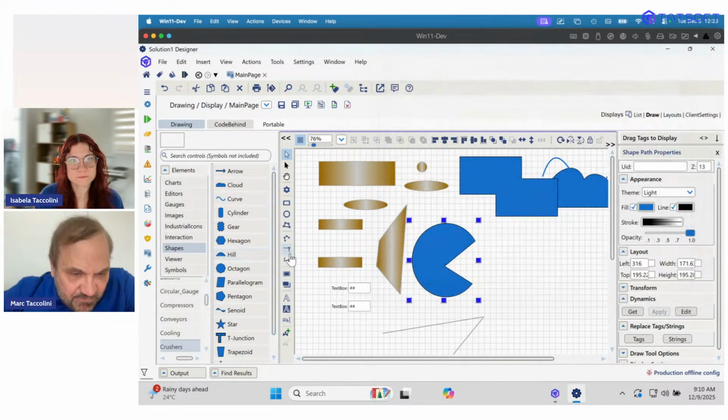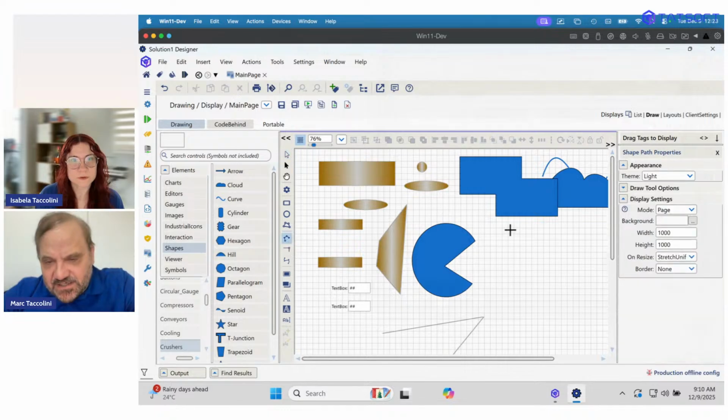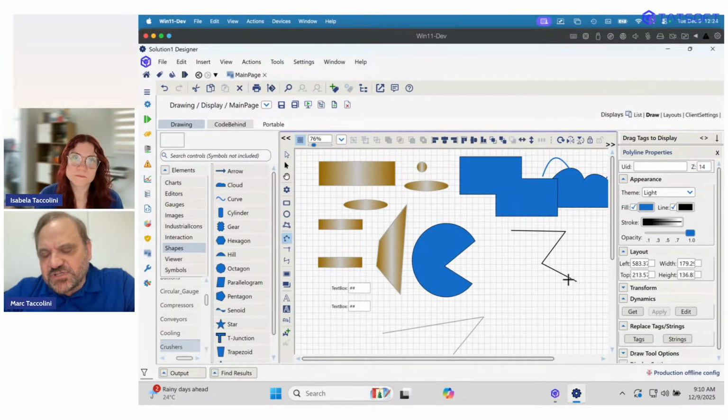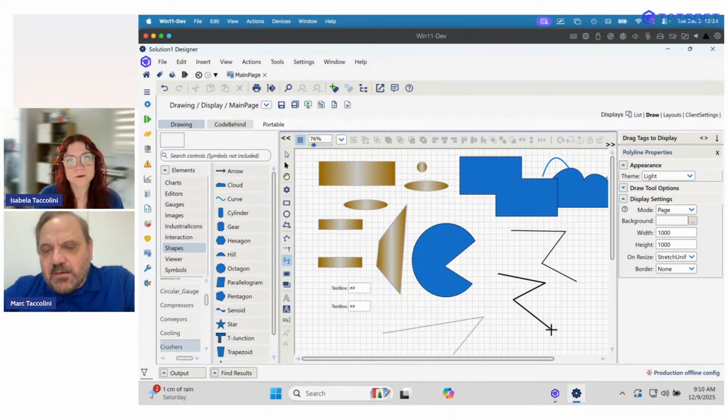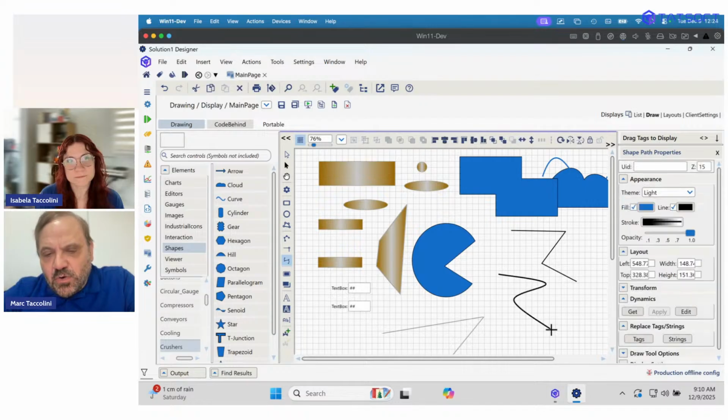But a path can be, for instance, a Bezier. If I do like that, I'm creating a polyline. If I select these other elements, very common in vector drawing, I select the points, but then I ask the system to create a mathematical curve called a sequence of Beziers, where the final curve is called a spline.